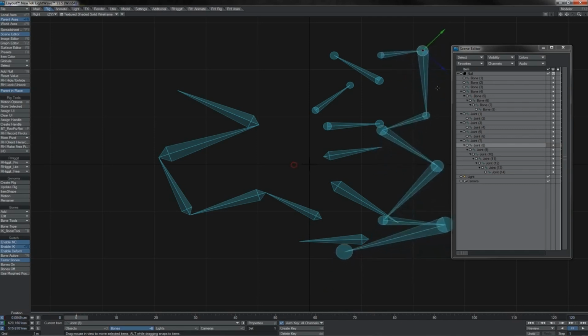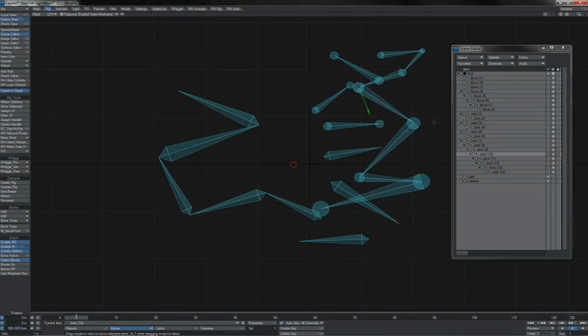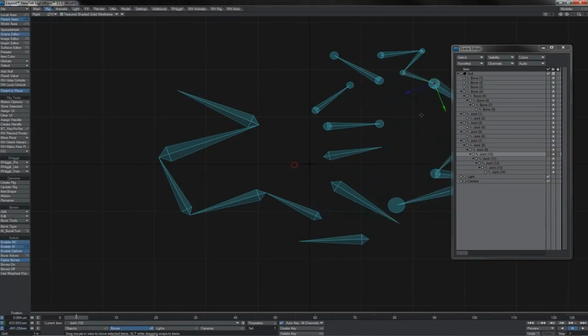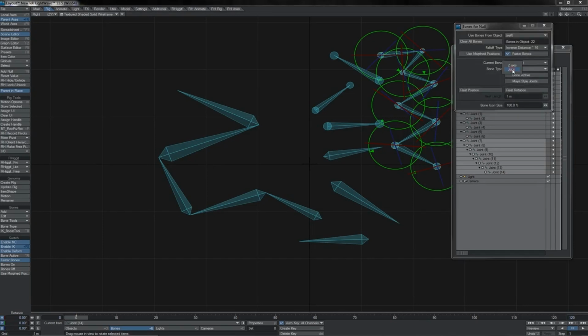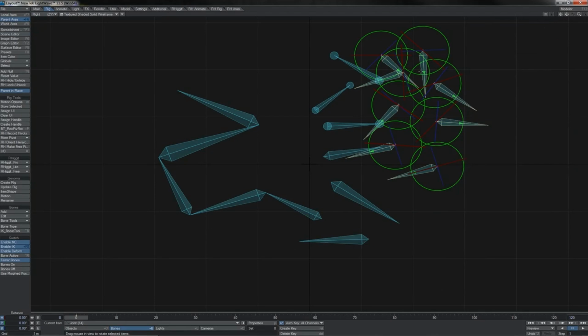You can have them positioned differently in this fashion, and when we are positioning joints around like this, what we do not have is LightWave aligning them for us. Moving this joint, as we will recall, is not rotating the parent, such that if we actually look at which way these guys are oriented, either by just looking at their rotation handles, or we can throw them over to Z-axis, again we see that their orientations hierarchically relative to one another are a mess.